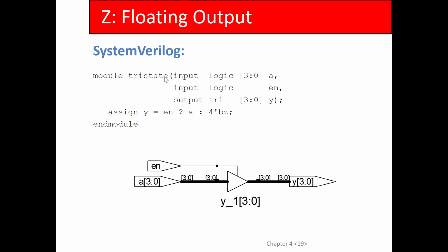You would get a warning, and maybe an error, but either way it wouldn't be good code because it would be unclear. Like if Y were 4 bits and A was too small, then what would assign the other bits of Y? It might create a latch. It would be unpredictable what the synthesizer would do in that case. On the other hand, if A was too large for Y, say A was 4 bits and Y was 2, would it just put the least significant 2 bits of A into Y and ignore the rest? Unclear. You don't want to write code like that.